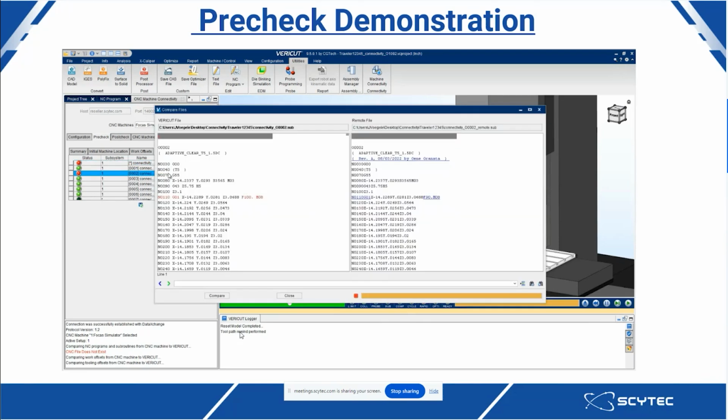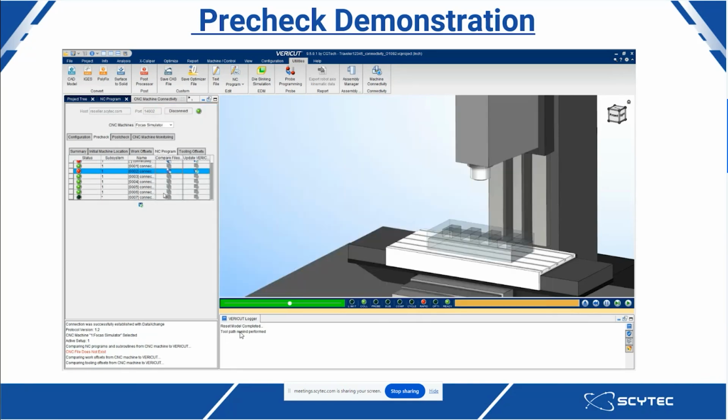The other advantage you can do with the comparison functionality here is you can look and see, and in this case, you can notice it looks like the feed rate has been adjusted from the program that's down on the shop floor to what we originally sent down there from VERICUT. So we'll need to address that as well.